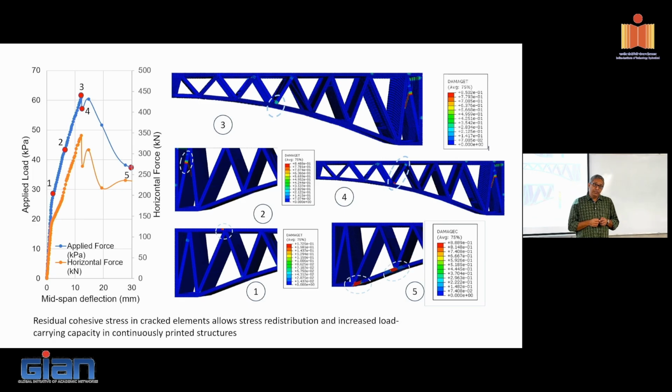Then somebody said, if you're going to put it on your campus, and the students are not exactly very friendly creatures, if somebody loosens the tie, the bridge is going to become unstable. So we eventually transformed it into an end-supported tied arch, where we essentially put the horizontal thrust onto an abutment. Right? But the idea still holds. The thrust that would be taken by a tension reinforcement is now going into the abutments.